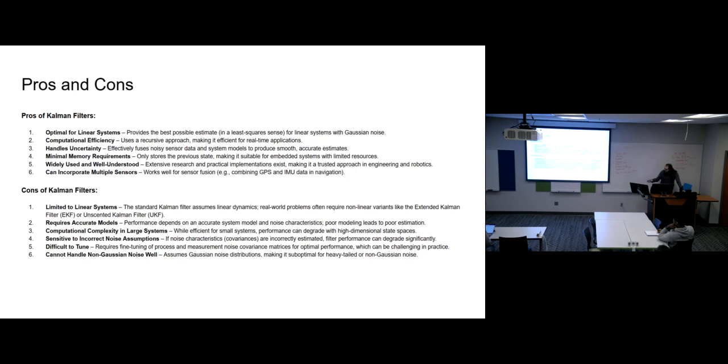But if you go to the extended Kalman filter or the unscented models, you can get around that. The difference between the extended Kalman filter and the linear one, in a simple description, is that the extended filter takes a Jacobian of your dynamics. As opposed to saying, oh, I think the car moves in a simple algebraic way, you're now making a differential equation, taking a Jacobian of your dynamics matrix and iterating over that from a state perspective.